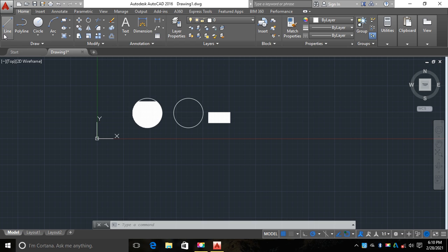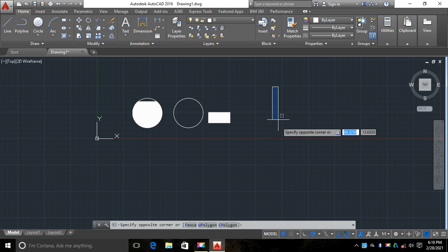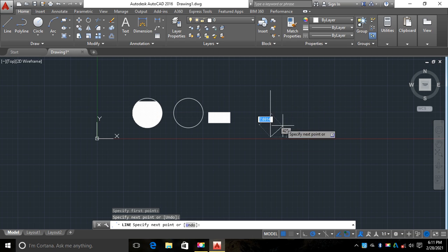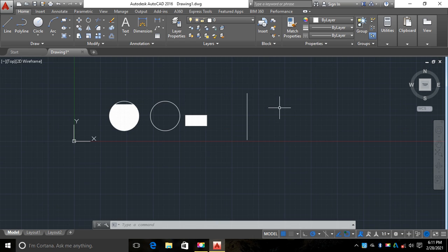Then if I have my items, let me draw some lines here. Sorry, you select a line. Let me say I have my line right there. So now if I want to make multiple lines, maybe with a distance of 10 between them, what I do quickly is I just offset this one line which I have here.